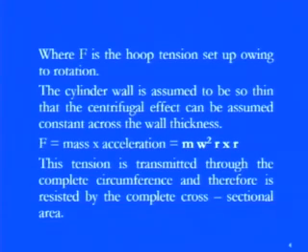That means whatever the centrifugal forces are coming, they are uniformly acting. So, whatever the deformation is, it is also uniform. That means there are no stress concentrations or distortions which are different at different regions. So, as you see, we discussed that the hoop tensions are there at the diametrical portion.